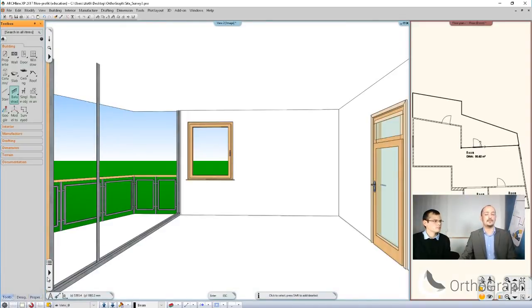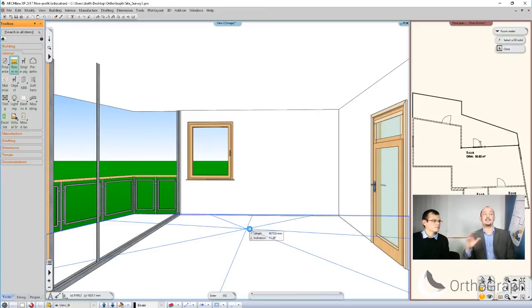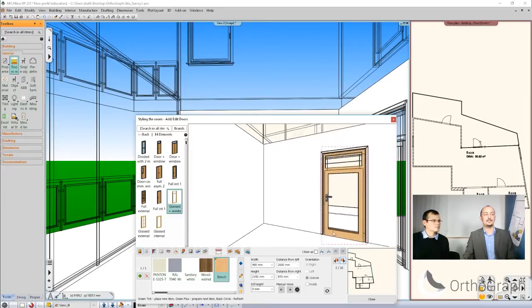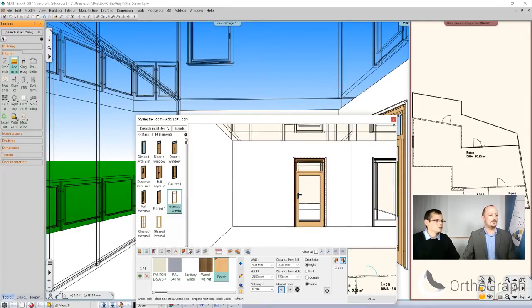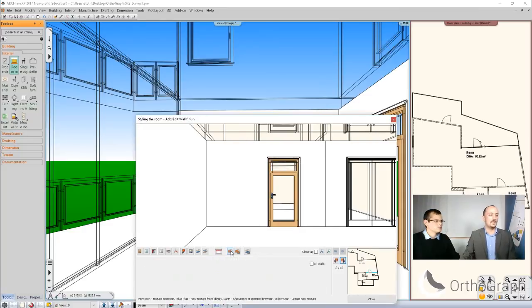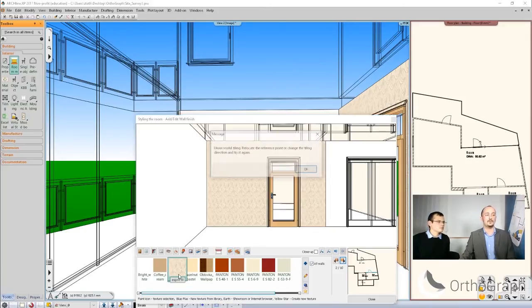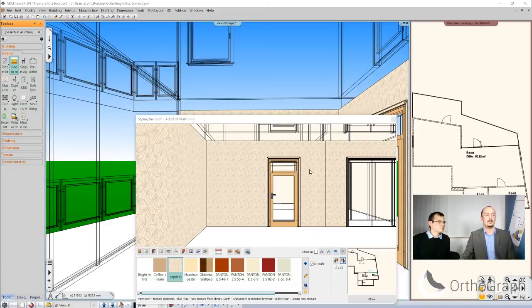Now, talking about the surfaces, we discussed that you can add additional surface features. You can use the interior room maker, for example, click into that room and decorate the surfaces. This will automatically load up, explore the rooms, and from wall to wall you can navigate with these two buttons. And then you can say that on this surface I would like to see, these are the tools here. I'm just covering the wall surfaces now, so I use that tool. That will be the color of it, or I would like to see it on all the walls, so I click on all the walls, and then it appears.